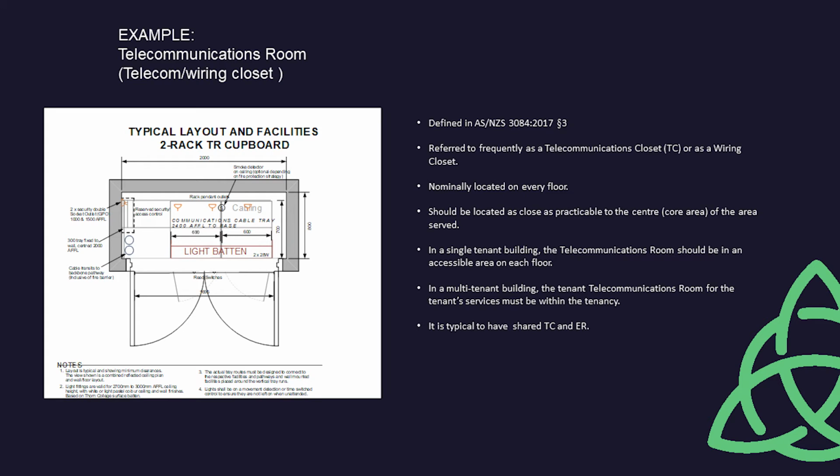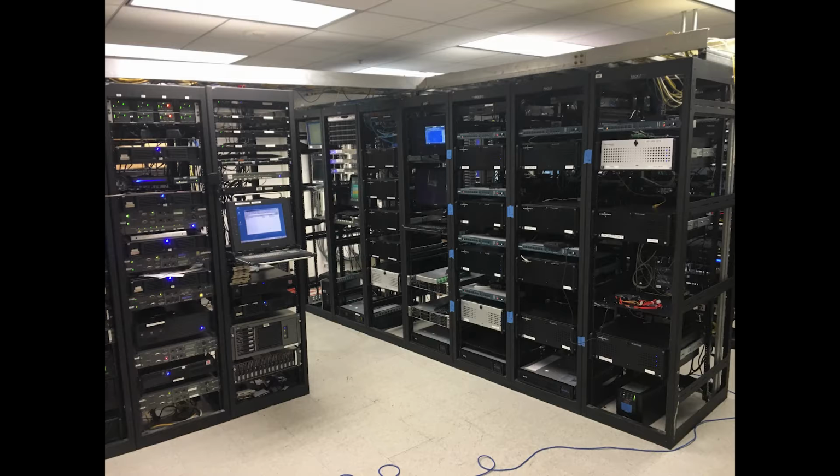The equipment room floor load capacity must be a minimum of 7.2 kilopascals to be able to support fully equipped equipment racks. Floors must be covered in a static dissipative material offering a smooth washable surface and a non-slip surface texture. Telecommunications rooms do not require anti-static floor treatments. The door to these rooms must be sized to allow an equipment rack to be wheeled into the room. Thus, the recommended minimum door size is 1,000 by 2,130 millimeters.